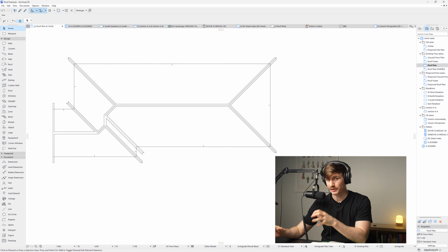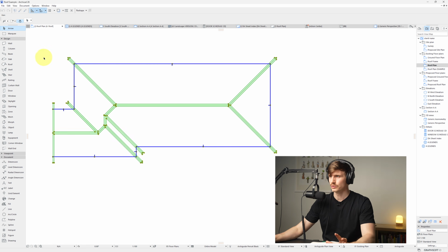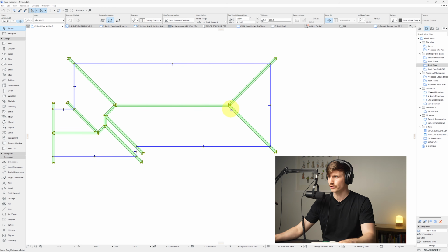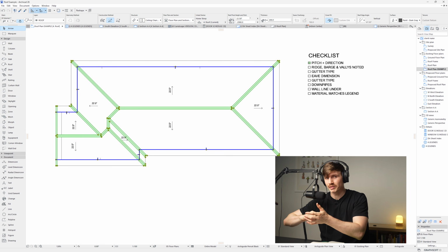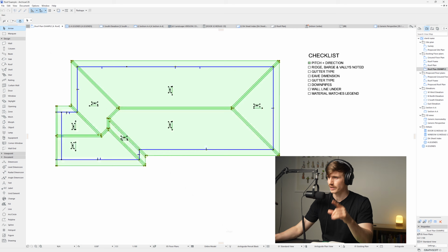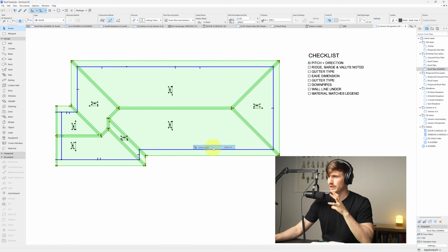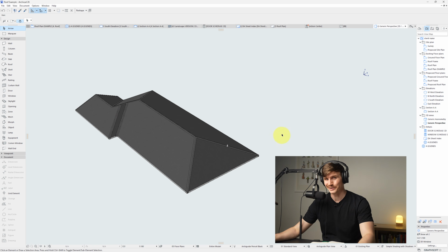All right, now that we've repeated that process for each of the roof planes, we'll now select all of our flashing. We'll go Control D and we'll raise it back that 20 meters that we set just before and go enter. If we pan back up, that set all the flashing over the top of the roof that we had before. Now, if we select everything, right click, and we go into our 3D, hey, there we go.